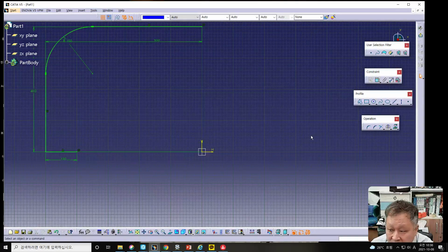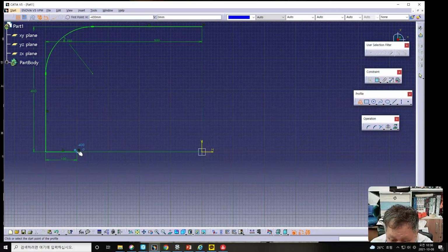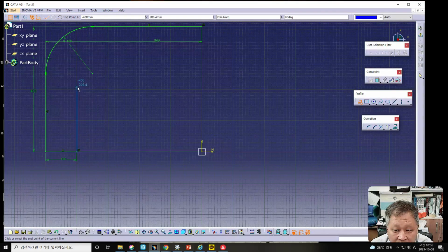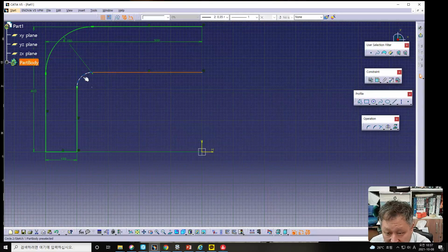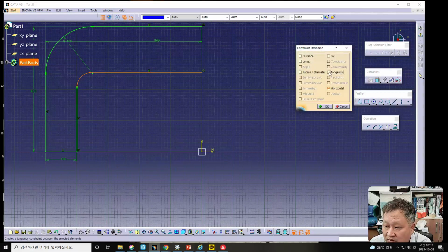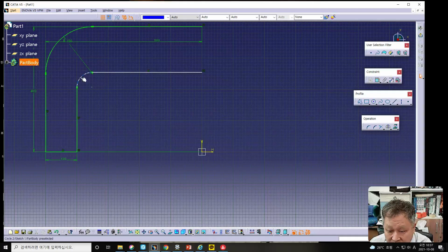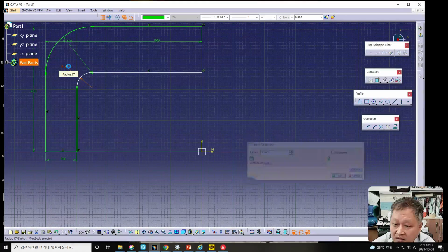In addition, the profile should be made from this operation, and a 3-point arc is needed. The profile should be accomplished in this operation, and this should have tangency alignment, as you know, and the radius of the corner should be 50 millimeter in this case.